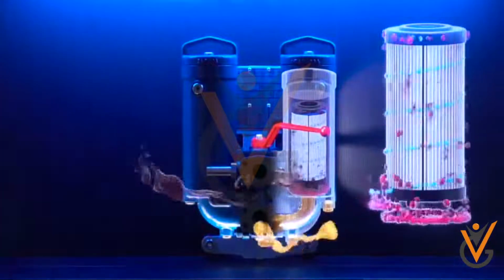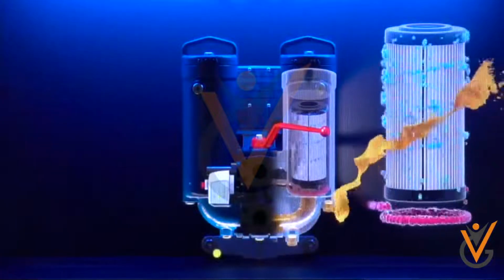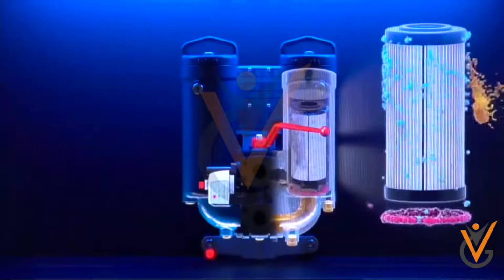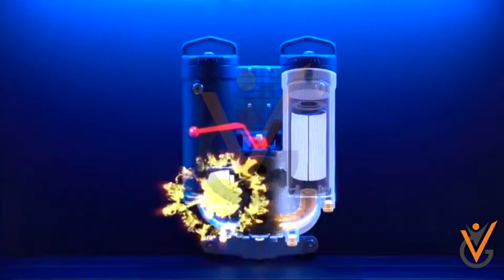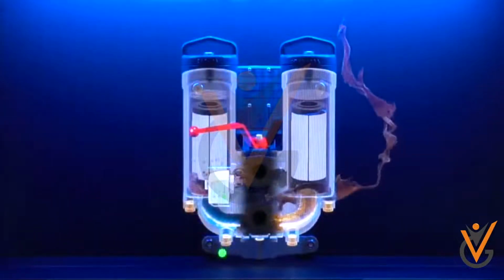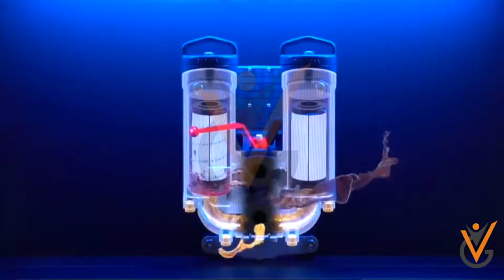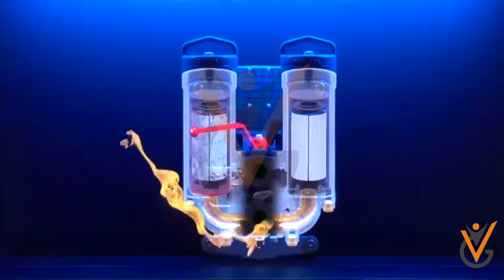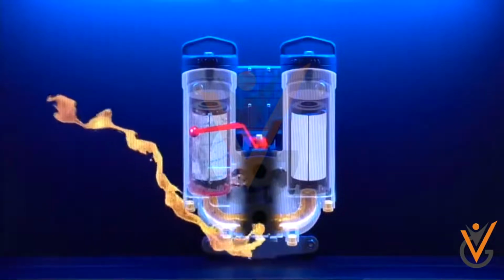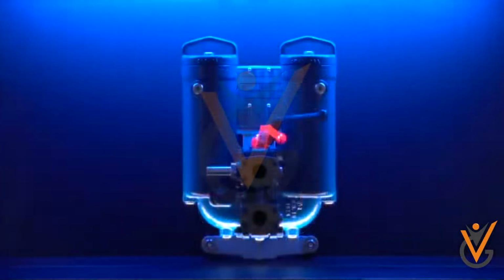Duplex filters are designed for the use of fluid handling where the flow cannot be shut down for basket cleaning or when the system becomes clogged. There are two separate filter basket housings on this system, and there is a valve handle between two baskets to divert the flow of liquid to one filter while the other is being cleaned. This creates maximum efficiency potential due to 100% uptime and no downtime.